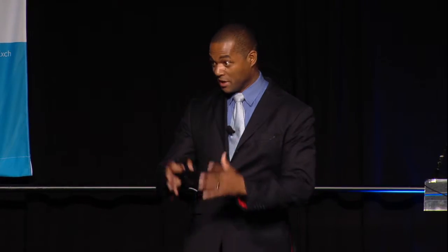So now we've gone from a minor troubleshooting checklist procedure that we train for all the time to, okay, now we're going to have to do some things and think about how they are going to affect our flight. The most important thing for us is to get another generator back online, because that battery, they tell you 30 minutes, maybe 45 minutes if you hold your nose just right and you pull all the right circuit breakers and things work out. So we went through the process and were able to get both generators back online. The reason is really not that important, but it got us thinking once we got on the ground.